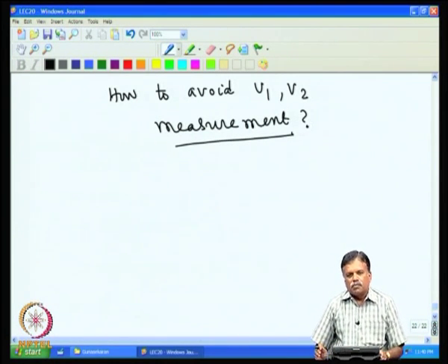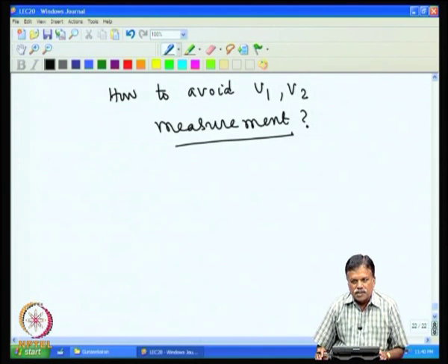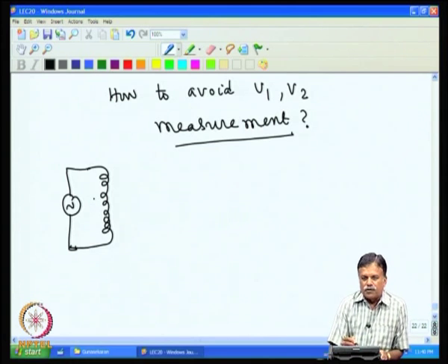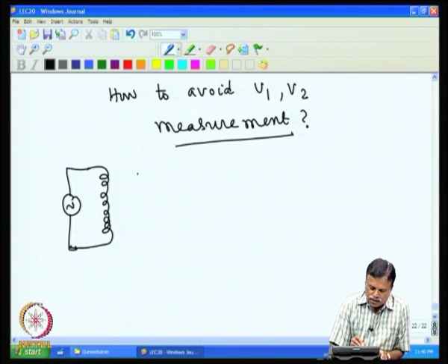This can be achieved by modifying the bridge. What can be done is that we can modify the ratio transformer slightly. You keep the primary of the transformer the same, you energize this with the low frequency AC source, then wind the first primary. Assume we have 10 turns here, that is you have 1, 2, 3, 4, 5, 6, 7, 8, 9, 10.